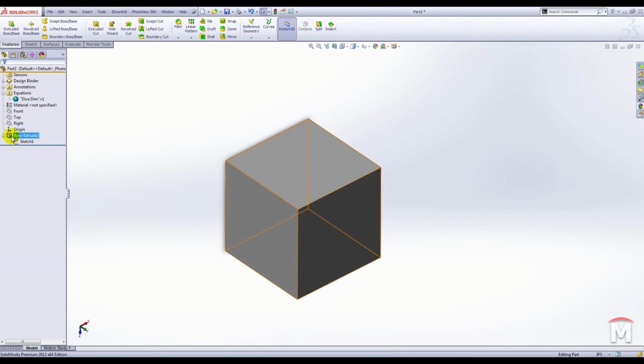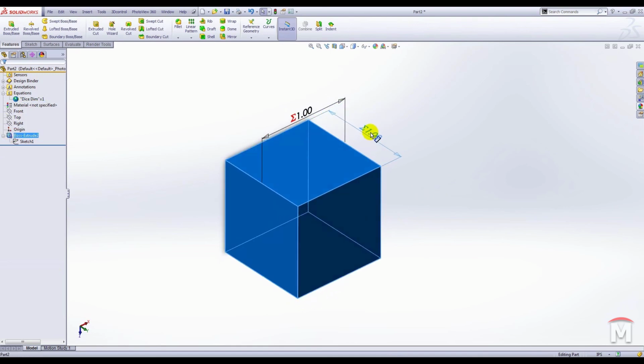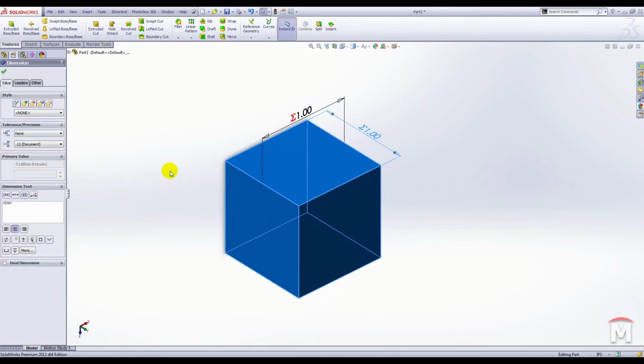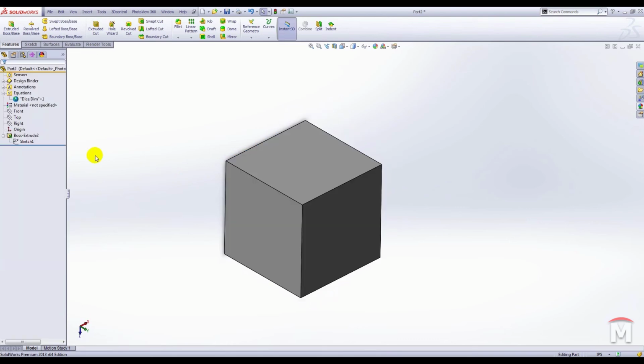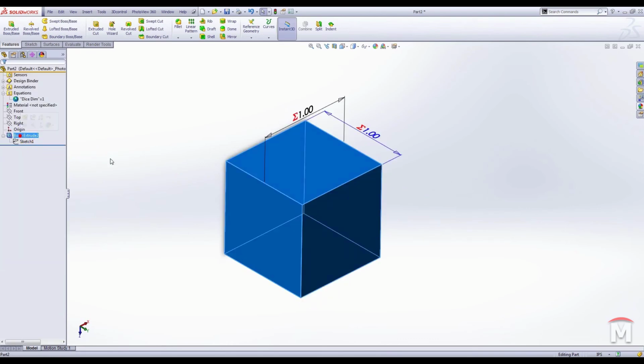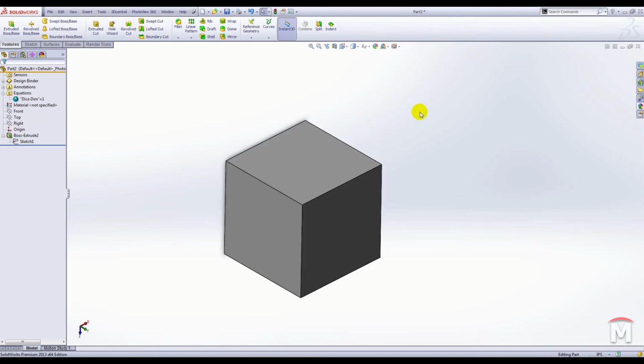Now Instant 3D, the green arrow is now grayed out because we don't have the option to drag this guy in space. So even though you do have that option to use that drop down menu just by clicking on the dimension box, make sure you understand that you're not linking it unless you type in that equals. You're not creating any kind of reference back to that point if you're not hitting the equal key.